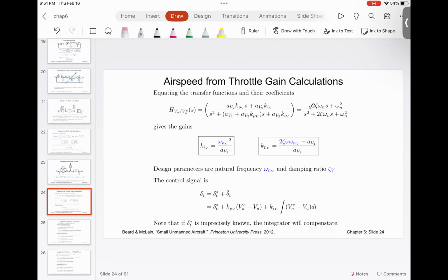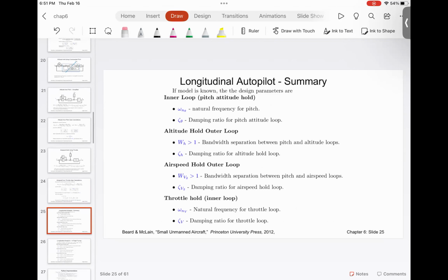Now, the next part is finding out the gains. The way you will do the gains is you can use this throttle delta T as a PID or PI controller. For example, this is the proportional control and this is the integral control that is used to make sure that the system doesn't overshoot. So you can use the KI control for controlling.